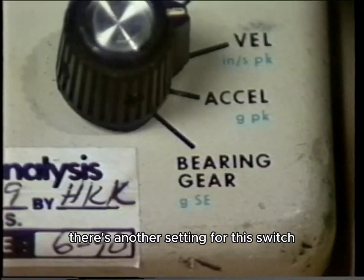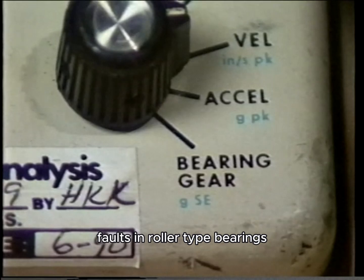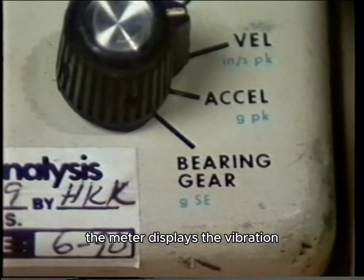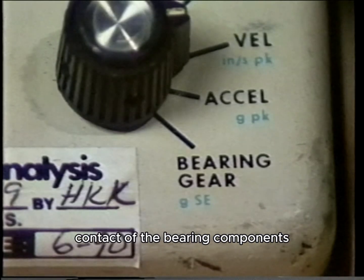There's another setting for this switch labeled SE on this unit that can be used to find faults in roller-type bearings. When the instrument is set at this position, the meter displays the vibration caused by metal-to-metal contact of the bearing components.